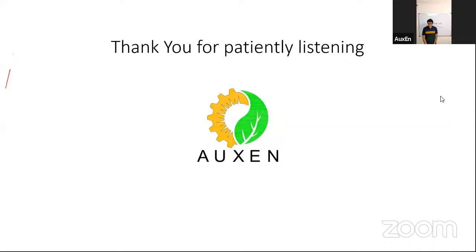Mr. Weber is asking whether detailing will be done manually or using CSI Detailer. So we will do the detailing manually as per the standard norms that we follow for our projects. Even if you go to any office, there are some standard norms that we follow for detailing. So we will do detailing ourselves manually, by taking the results from ETABS or SAFE and doing the detailing part on our own.